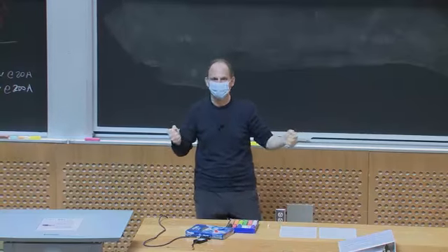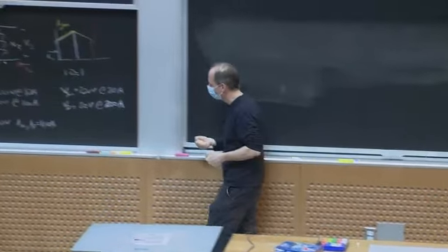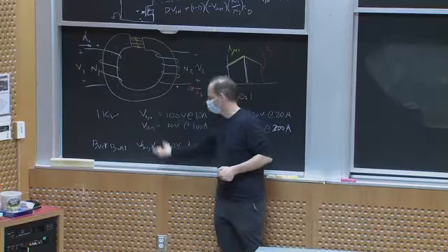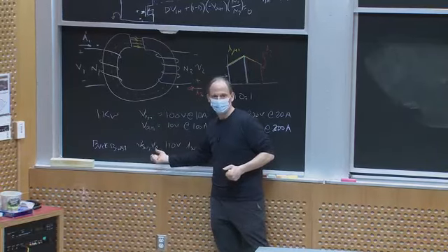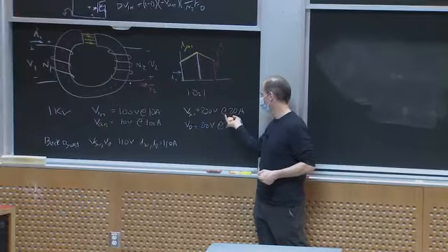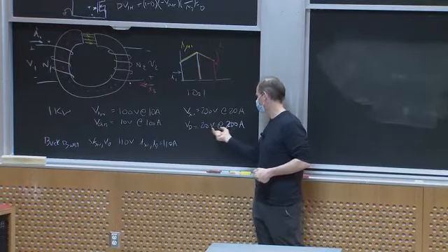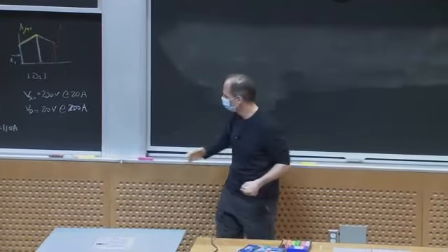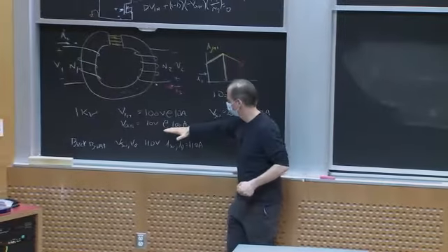If I just thought about it in terms of kVA, this is sort of 4 kVA instead of 12 kVA or something, right? So it's much less VA, but it also means I can go pick a high voltage low current switch and a low voltage high current diode, and this would be easier to source.